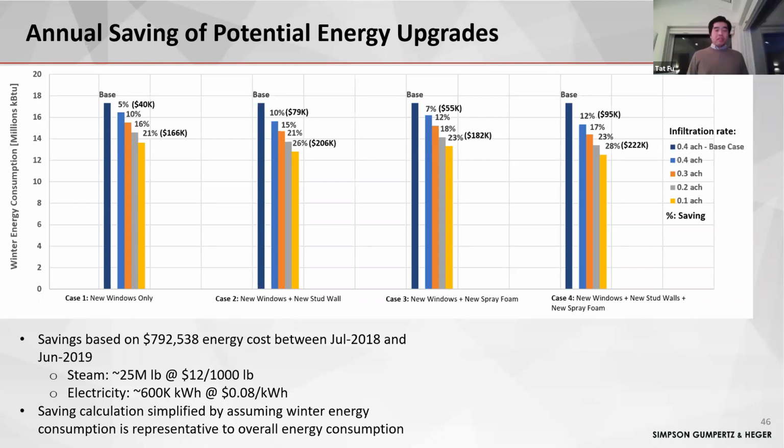That's actually a very good question. And we didn't have too much time, so I kind of glanced over that. I briefly mentioned when you upgrade the window, you will improve your air leakage, because windows, especially windows that are getting 20-some years old, start to get quite leaky. The gasket, the weather strip around the window just starts deteriorating. And so that's one area that you can improve the air leakage with.